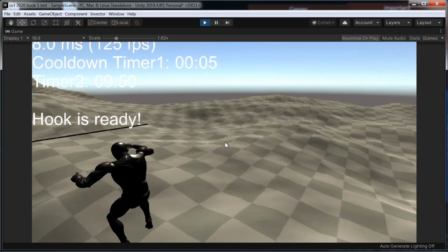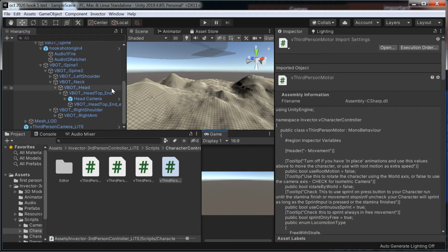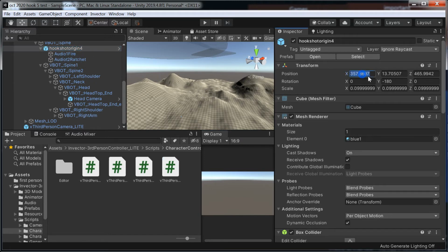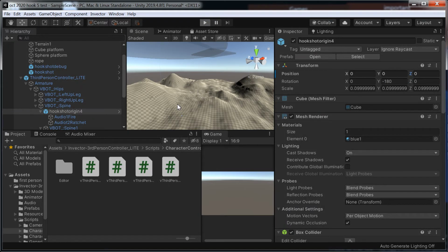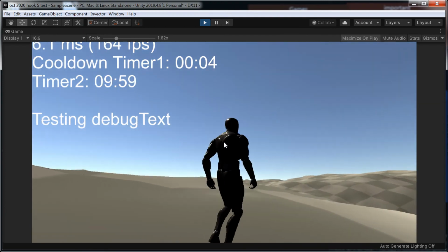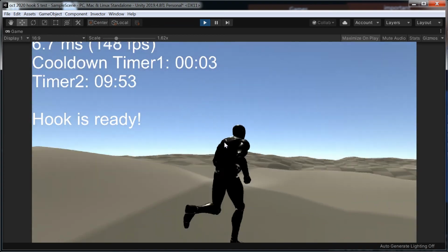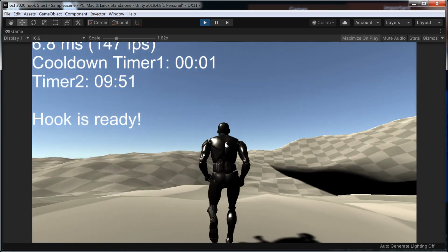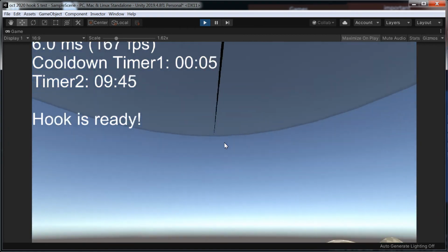well, it does this sort of business. I've also noticed there's an error there with the origin. It's offset. There we go. So we've got to make sure that those are set at zeros so that the origin is locked into the spine. It can't have its own coordinates. That was caused by dragging it in. They are set at 0 from the import, but when we drag it again from the prefab, it mixes up numbers.